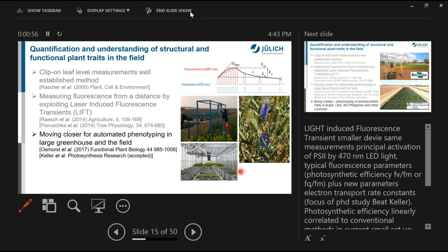And through the same lens, we have different fiber optics leading in, and we feed the laser in the same optical path by different beam splitters and light splitters. So we again make use of the different spectral properties. We have different spectral responses of the light splitters, and we actually shoot the laser exactly through the same optical path as we measure the fluorescence light back to the instrument. And therefore we are overcoming the problem of the alignment.